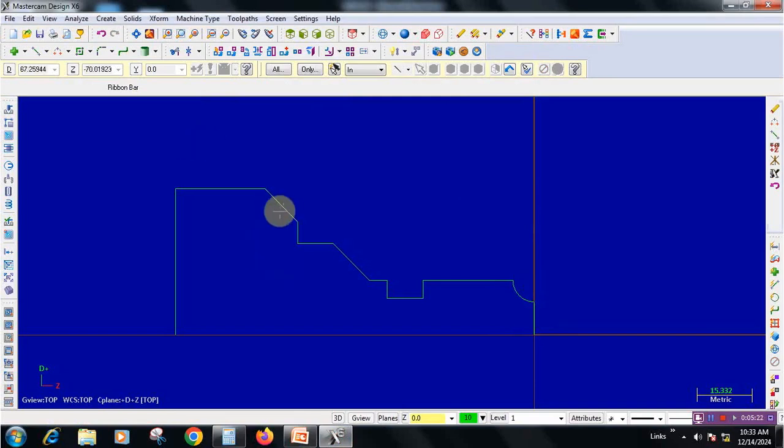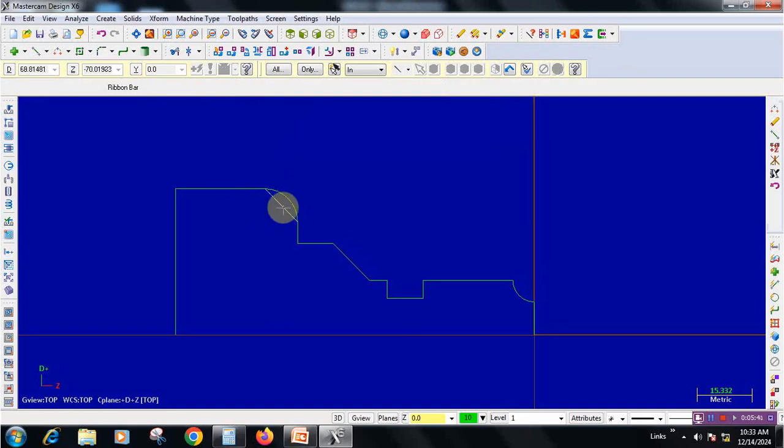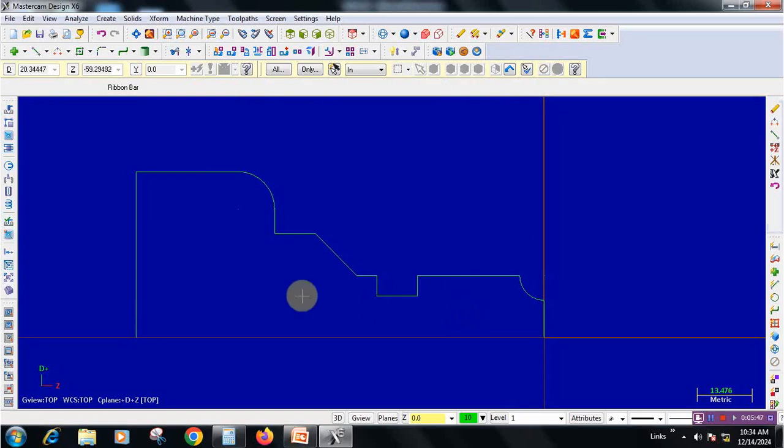And one more curvature here, select arc endpoints, click at 2 points, enter the radius as 9. The same procedure, click on the profile. Okay. Now we need to delete the line, simply select the line and directly delete it. Say almost the profile is over.